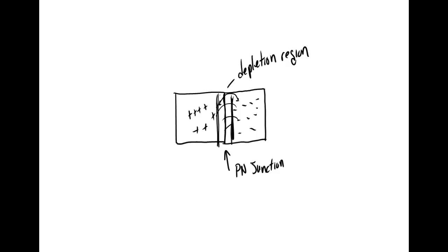Now what this does, it creates a charge across the junction. And it ends up creating a little battery in there. Now the silicon in the depletion region has so much opposition right now that it can't produce any current, but we can measure it with our meter. Our meter has about 10 megohms worth of resistance on it. So we can measure this voltage, and we refer to this as the barrier voltage.